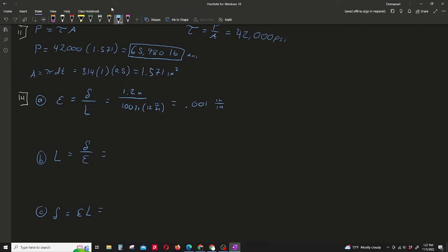Down here we have 0.5. Again, make this times 12 divided by our epsilon, which they gave us 0.00030, and that's going to equal just 20,000 inches. Or if you want to divide that up, we get 1667 feet. And then lastly here, they give us L as 1,000, epsilon is 4.2 times 10 to the negative 4, or whatever it is.